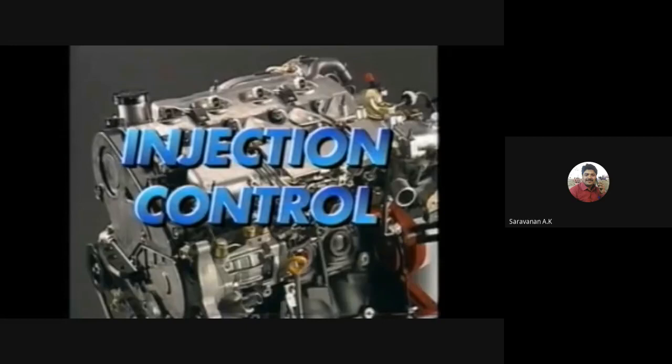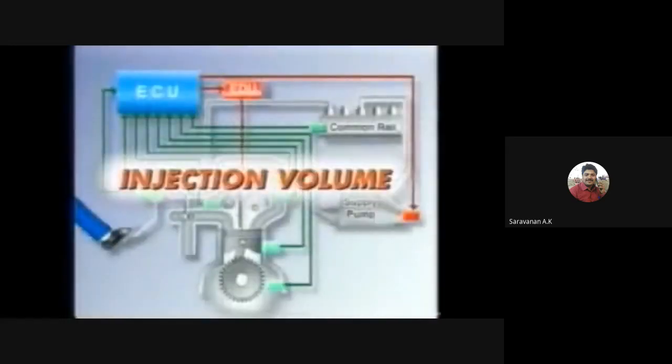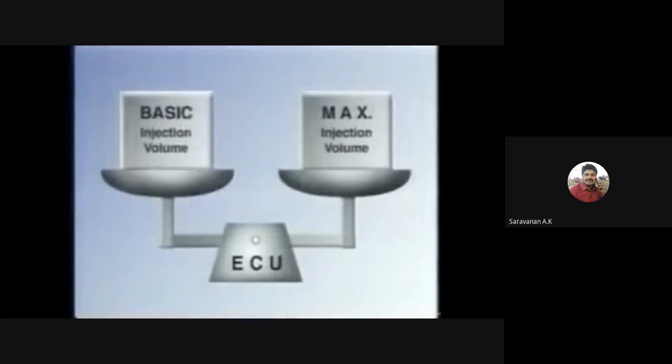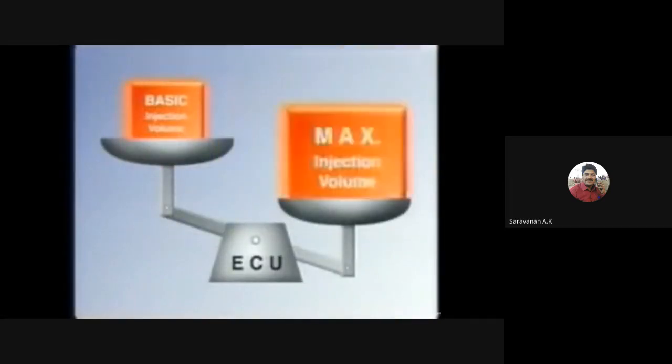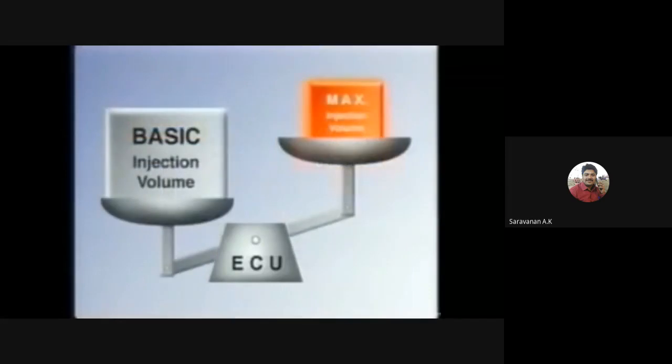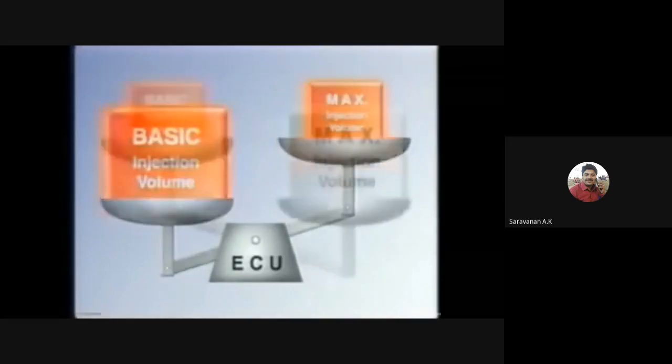How does the ECU determine the injection volume and timing? Let's first look at the injection volume. The ECU calculates the basic injection volume and the maximum injection volume, and whichever is smaller is determined to be the actual injection volume.